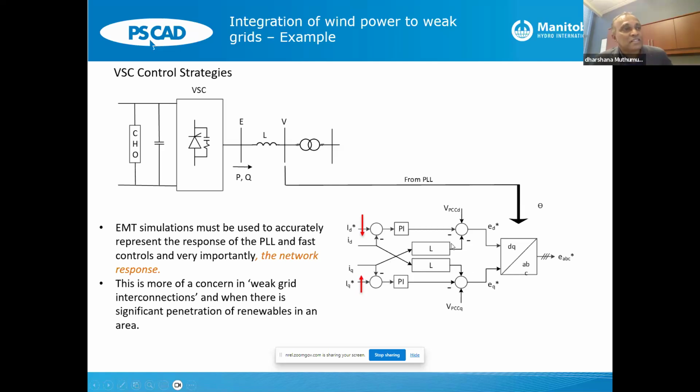And finally, the controls will establish a so-called D and Q axis voltage reference for firing impulse generation. Of course, D and Q axis quantities are mathematical. At this last stage of the inverter controls, you have to convert ED and EQ to the ABC reference.